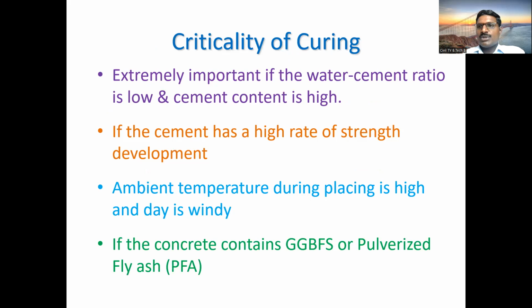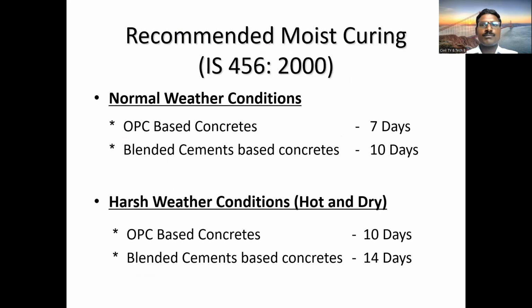So as I told, curing is very important. It is extremely important if the water cement ratio is low and the cement content is high, if the cement has a high rate of strength development, if the ambient temperature during placing is high, and the day is windy. As I told, 30 to 40% of strength is increased by curing.